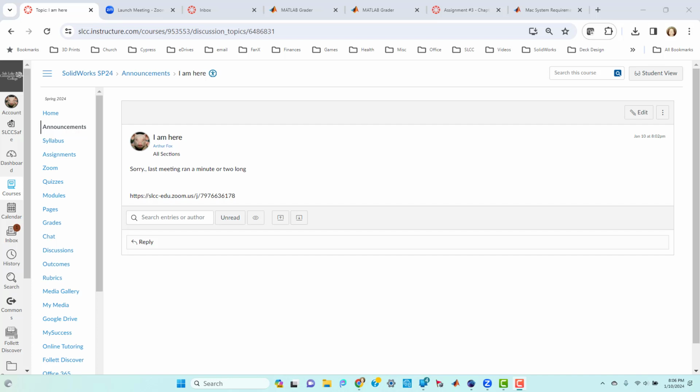Flatter Files will go into my PDM vault and look for every drawing that has been approved in PDM. What's PDM? PDM is project data management. It's a caretaker for our SolidWorks files. You check in files, you check out files, you approve files, you disapprove, and so on. But anyway, it goes through and finds every approved drawing. It then creates a PDF of that drawing, and it creates a step file and an IGES file, which are the two I specifically specified, because that's what our vendors want.